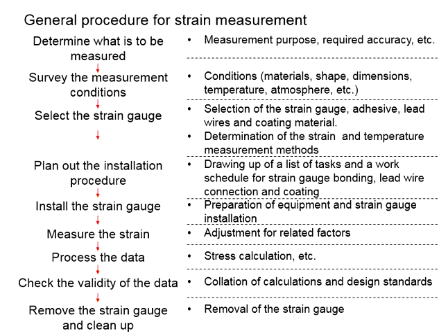You might also need to check the validity of the data through calculations or some design standards to see if the data is reliable. Always be skeptical with the data. You cannot assume all the data are right and reliable. Maybe you overlook certain procedures. Whenever you acquire the data, check if the data is logical and cross-check with the other aspects during the testing.